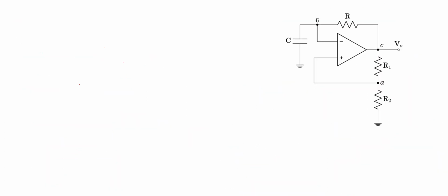Now we'll see how we can implement an astable multivibrator using the Schmitt trigger circuit. So from the previous circuit, one change that we have made is that we have withdrawn the manual voltage source and we have given the resistance and capacitor here, and positive feedback remains and there will be a negative feedback too. So how does this work? Okay, let's see.